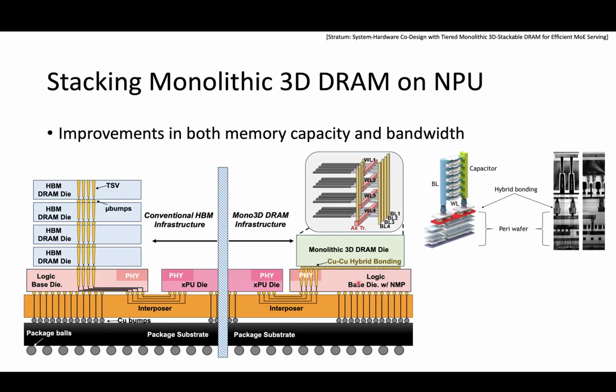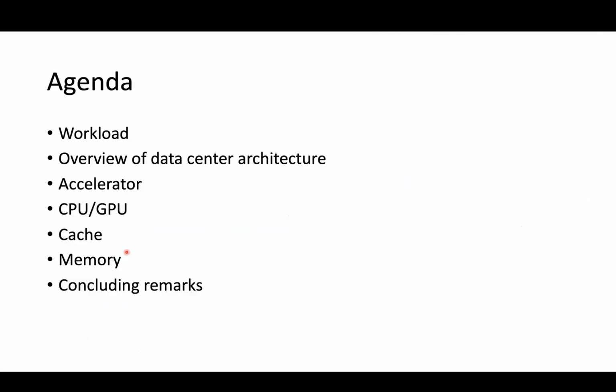In the case of HBM4, the reason why we could increase memory bandwidth is basically hybrid bonding between the memory die and the logic die. In the case of HBM4, we use hybrid bonding here. In order to support a large number of wires, we need more TSVs.